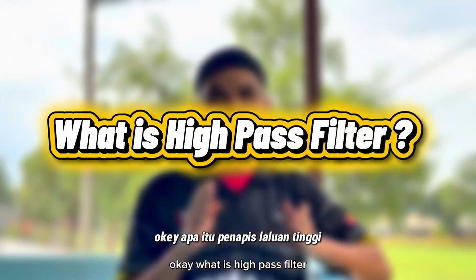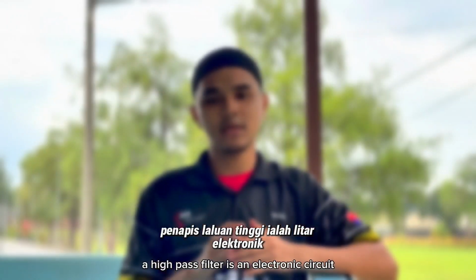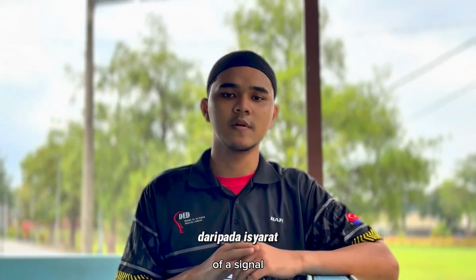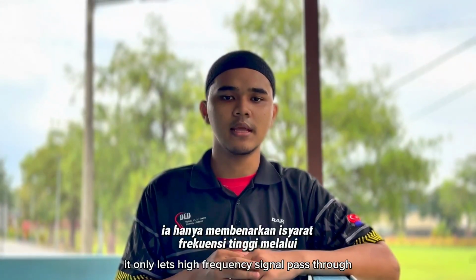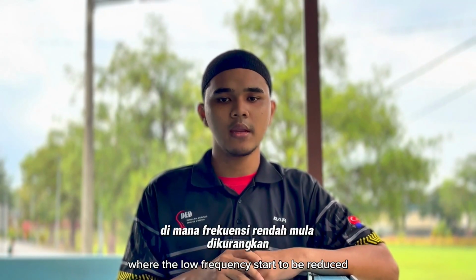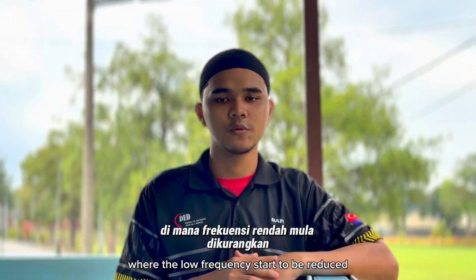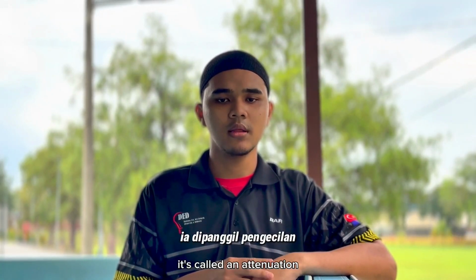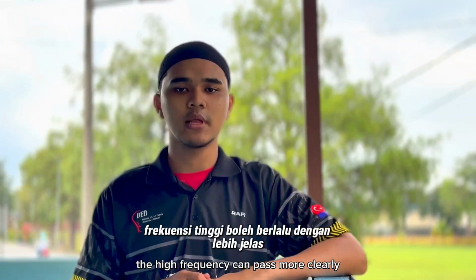Okay, what is a high pass filter? A high pass filter is an electronic circuit that removes the low frequency part of a signal. It only lets high frequency signals pass through. The cut-off frequency, Fc, is the point where the low frequencies start to be reduced. When a signal is reduced in range, it is called attenuation. By reducing the low frequencies, the high frequencies can pass more clearly.